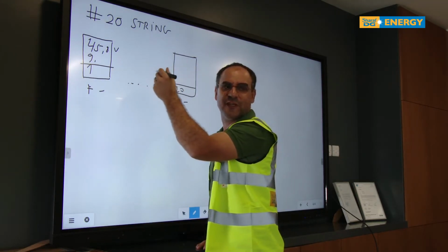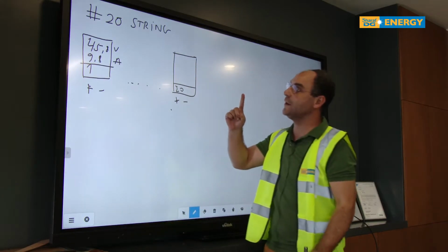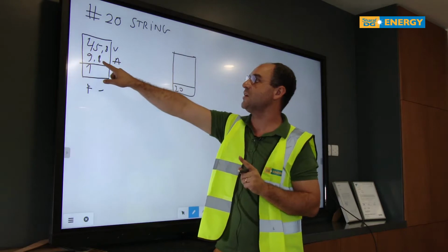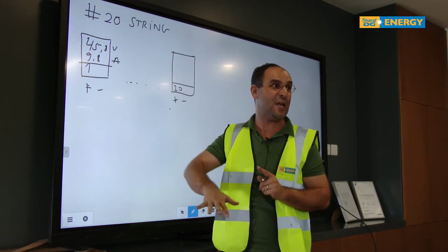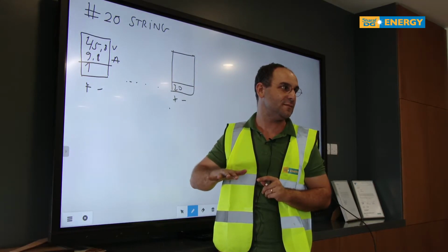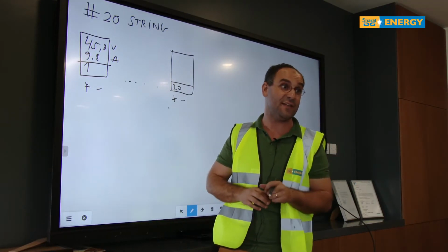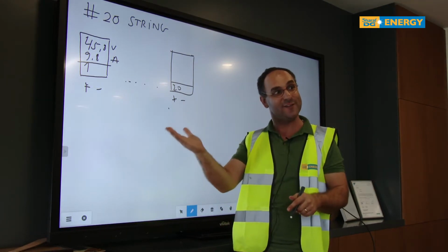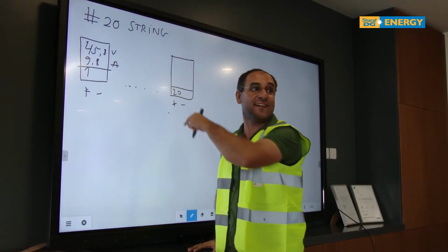9.8, let's say 9.8, right? Amps, okay? So each panel has an open circuit voltage of 45.8 and a short circuit current of 9.8 amps. This is physics. No one changes this. And this has been certified by third-party guys, all right? That's why you buy the panels, because someone told you that you can buy these, because we trust their technical sheet.